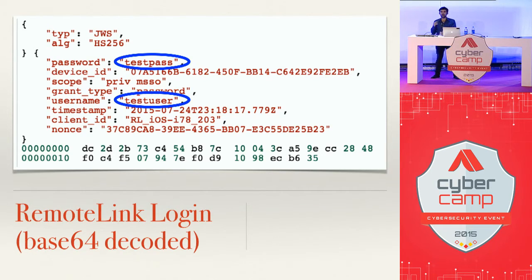However, because they weren't actually doing certificate checking or SSL certificate checking properly, I was able to do the man-in-the-middle without any certificate authority at all. That means an unmodified device, an unmodified iPhone, can get attacked. You can perform an SSL man-in-the-middle attack and extract someone's username and password. And because it's always sending either the username and password or authentication, once you get that once, you can then log in indefinitely into that car,